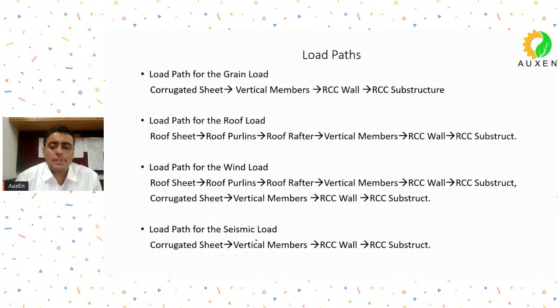Load path, just for our understanding. So when you have the grain load, first, of course, it will act on the corrugated sheeting. From the sheeting, it will be transferred to the vertical member, then to the RCC wall, then to the RCC substructure.